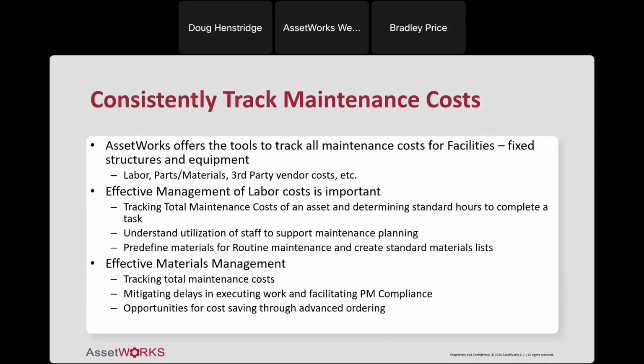So again, an example from a customer I've worked with, they maintain in each of their mechanical rooms the next set of filters and a spare belt for their air handling equipment in the box in the room. So when they schedule their PM for that, they know they have the materials on hand. They can go and they can schedule it. They can go and do it. And when they do it, that's a trigger to reorder the next set that they store in the room, so they're ready to go for the next time.